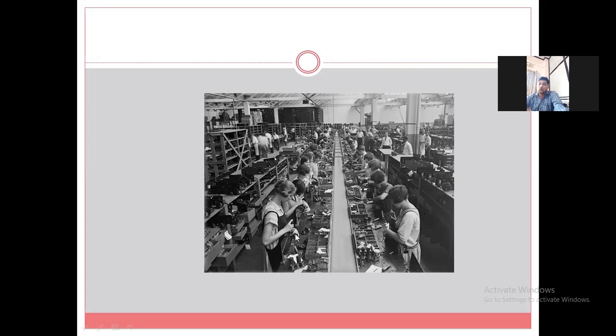Okay, now after 10 minutes one component will be released from this workstation to another workstation. After 10 minutes, this second workstation will perform the task in 8 minutes only. But till then, the second workstation does not receive the next component to perform the task. So for 2 minutes this second workstation will be in an idle condition, and that idle condition will be considered as a production time loss.